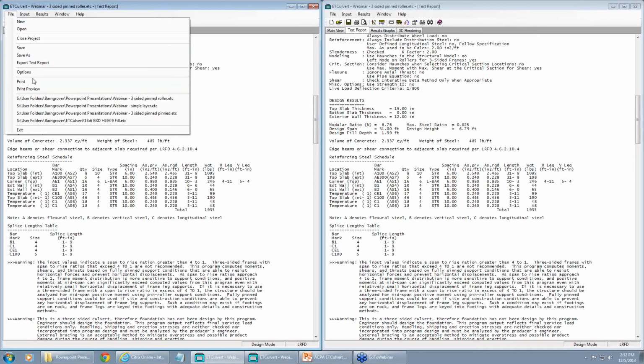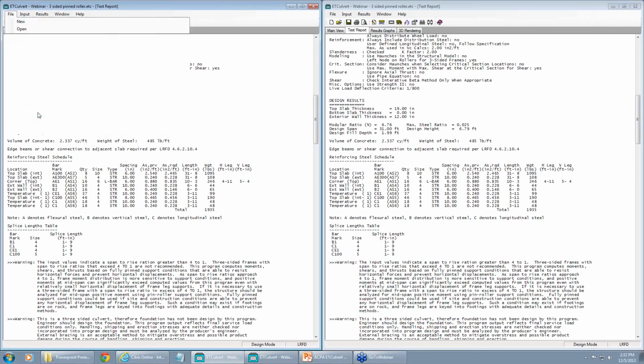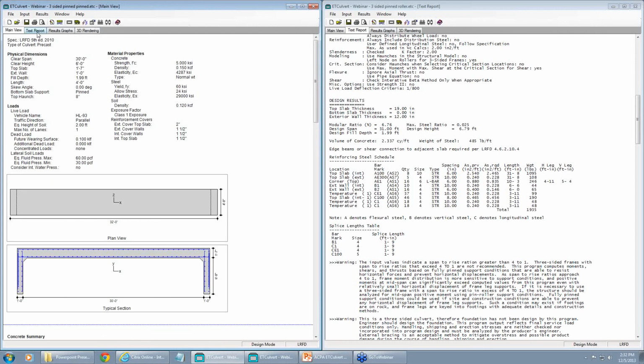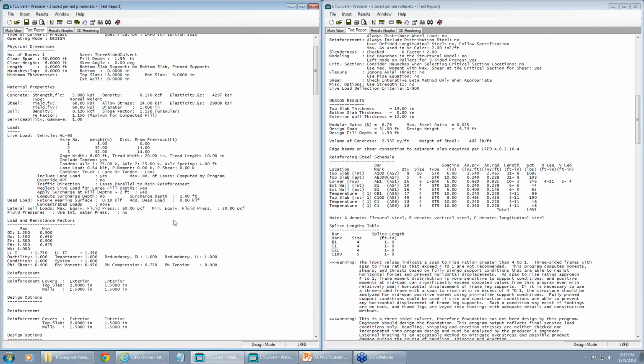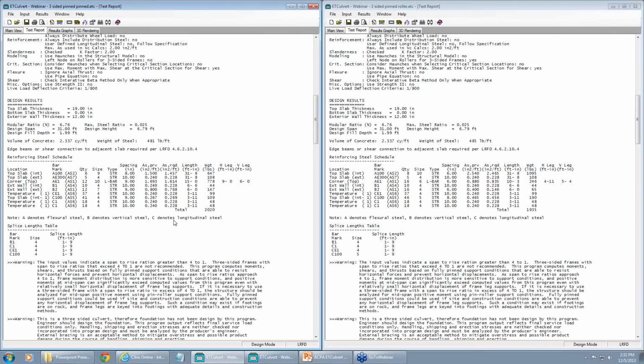I'm sorry, the left side is acting as the top member of the rigid frame. And so you'll see a higher negative moment there, all right? The right side over here, the top member is acting more as a simple supported. So you'll see more positive moment still in that one, and that will give you a good bound of your problem right there.